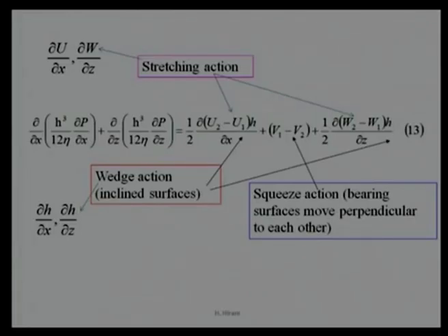To some extent, when there is a plastic flow or a viscoelastic flow, then these terms will be there. We say velocity gradient along the x direction and velocity gradient along the z direction are generally not possible, but will come if there is a viscoelastic flow or viscoplastic or plastic flow. Maybe polymer bearings also, where it can be accounted for.